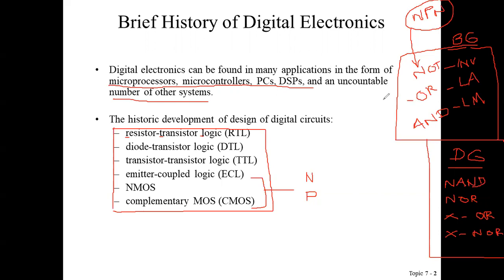And then the explanation of OR logic, I am going to explain RDL. RDL in the sense of using resistors and diodes to obtain the truth table or output of an OR logic. If we obtain the output of an OR logic using resistors, diodes and switches, that is RDL, resistor diode logic families. Okay? Which elements you are using to design a logic family, based upon that are the classifications.